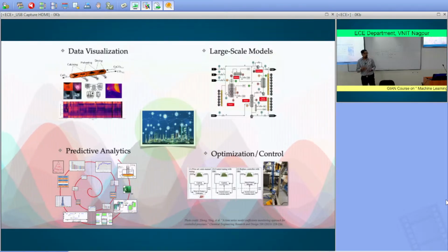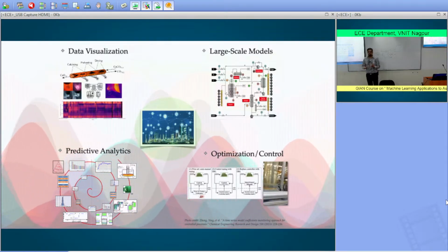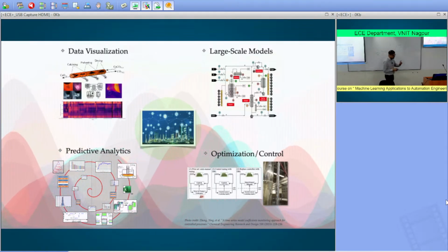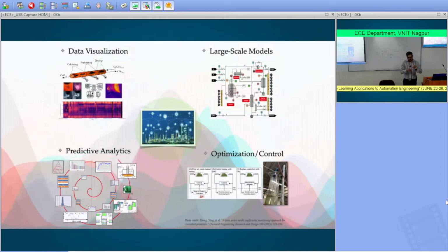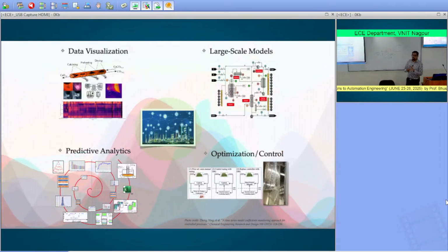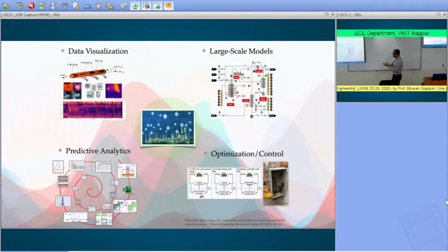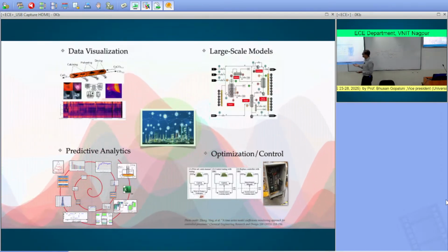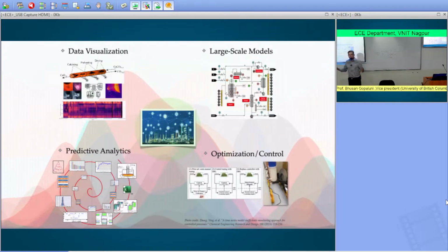And we don't know when that resistance changes, and when that resistance changes, the electrodes lose the arc at the bottom. Okay, and when they lose the arc, you break the circuit. The furnace has to be shut down and restarted.